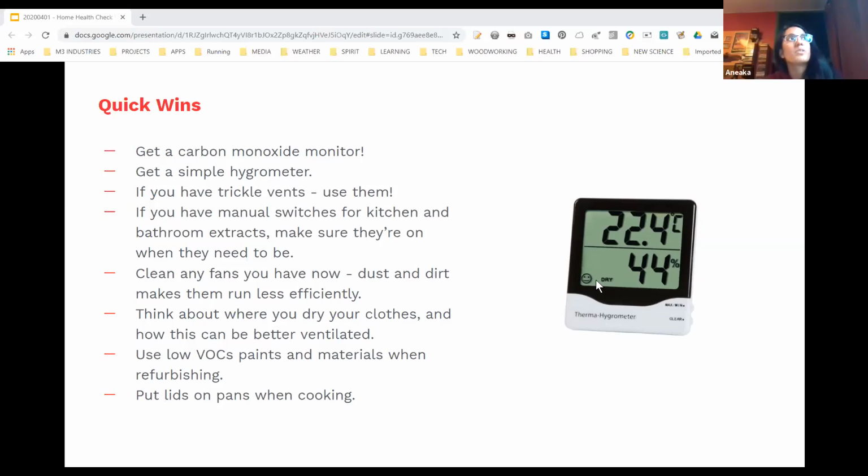There's also some people who put loft lids, little caps you can put on top of your downlight from the loft side and seal them in and put insulation over the top of them. Absolutely, and it can be done even easier by putting a board between the adjacent joists, putting insulation up to the edges, and then another layer of insulation on the top.